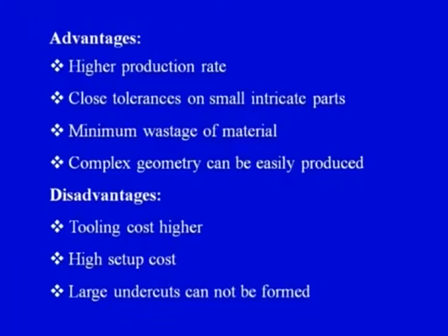But still there are a few disadvantages. Tooling cost is higher: the mold or die used for the injection molding machine is very expensive, because it has to have certain specific arrangements. One of these arrangements we have seen is the ejector pins, which are operated mechanically. So, the cost of the tool is high, which is one limitation.